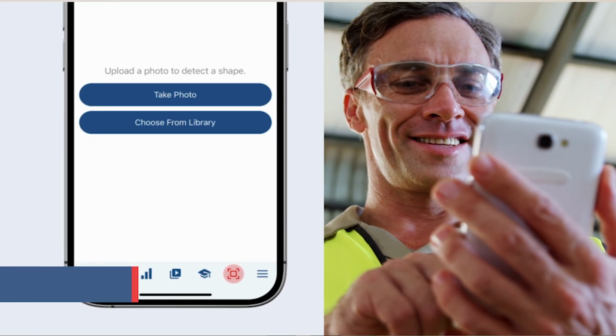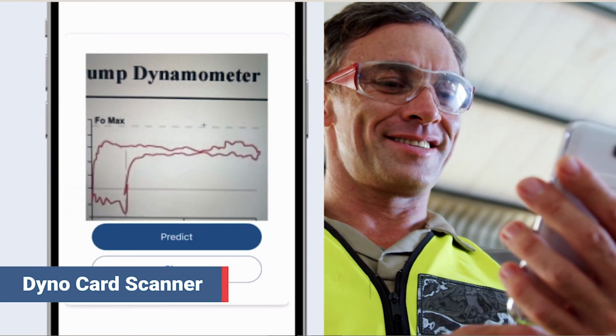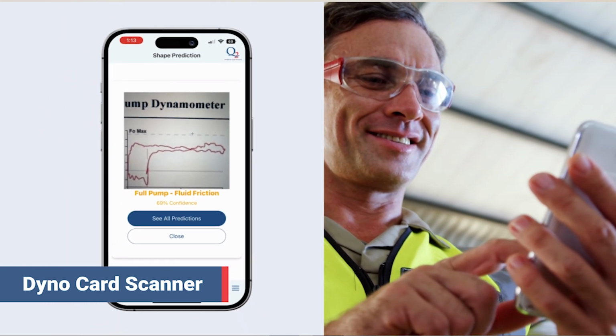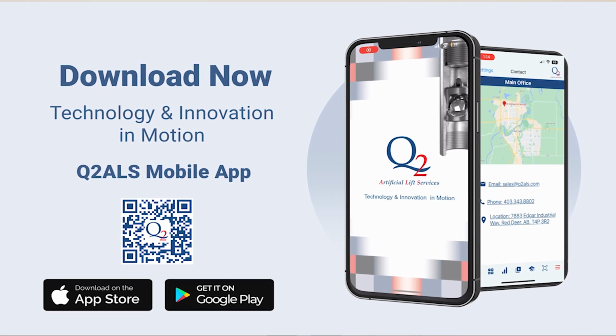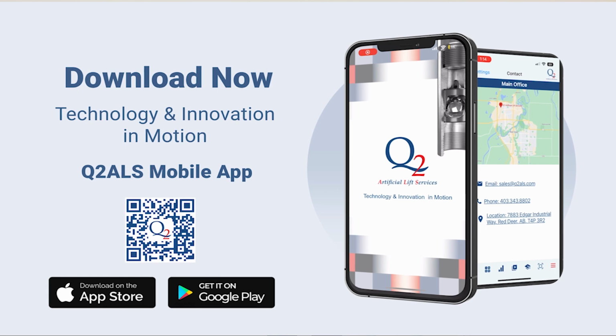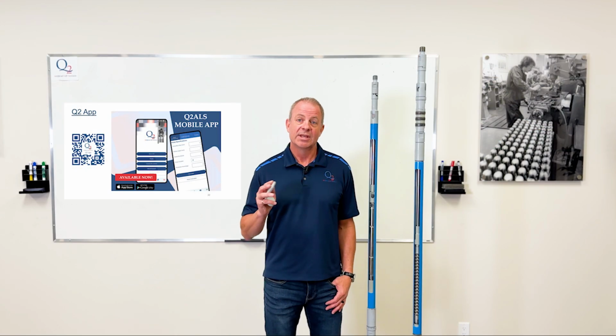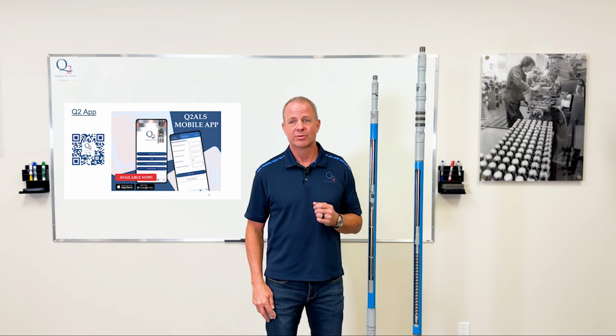And you also have an AI machine on our new phone that looks at a snapshot of a dyno and says there's a good chance you have fluid pound, you've got gas interference, you have a travel valve that's sticking, or what have you. So it gives you an idea of what's happening in your well. It's a really interesting app.